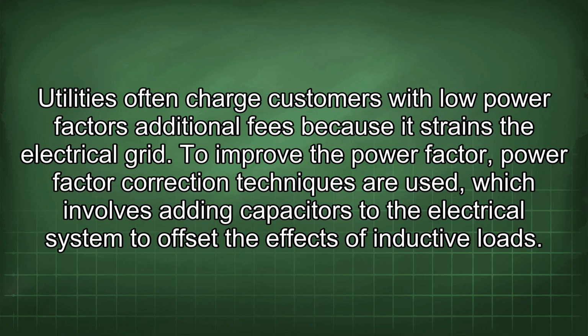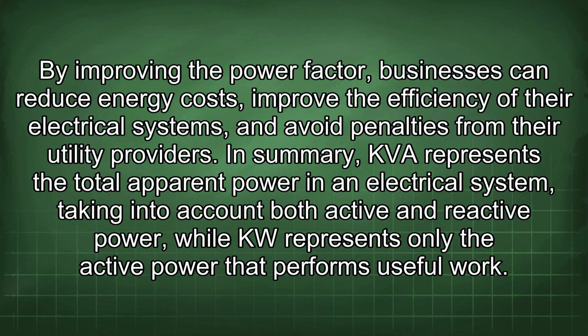Utilities often charge customers with low power factors additional fees because it strains the electrical grid. To improve the power factor, correction techniques are used, which involve adding capacitors to the electrical system to offset the effects of inductive loads. By improving the power factor, businesses can reduce energy costs, improve the efficiency of their electrical systems, and avoid penalties from their utility providers.